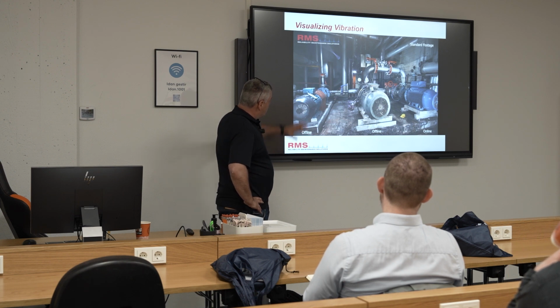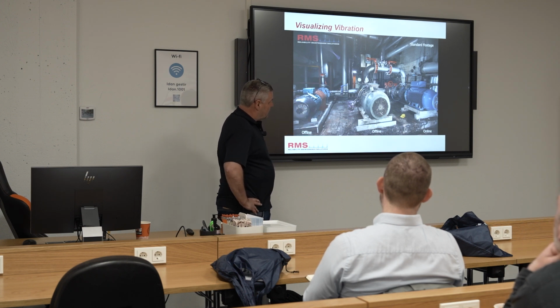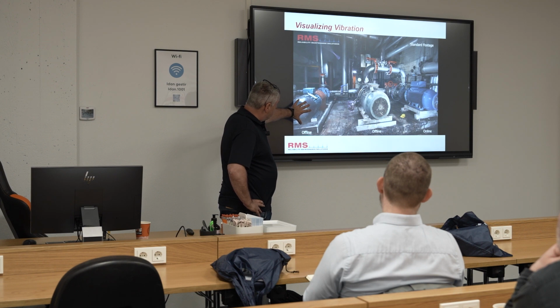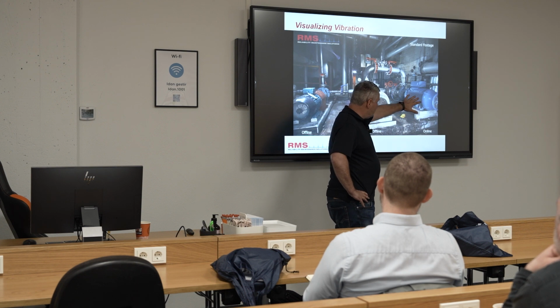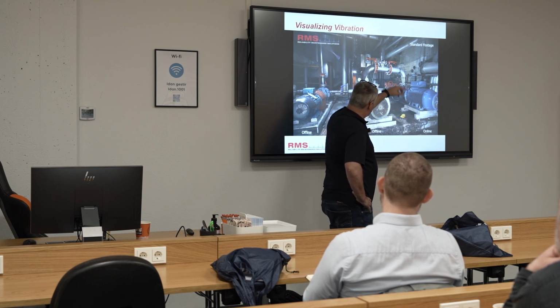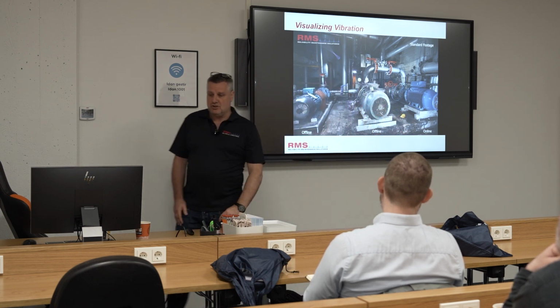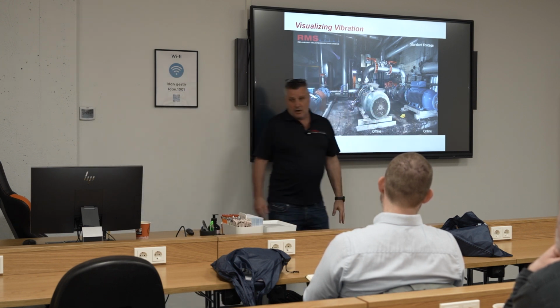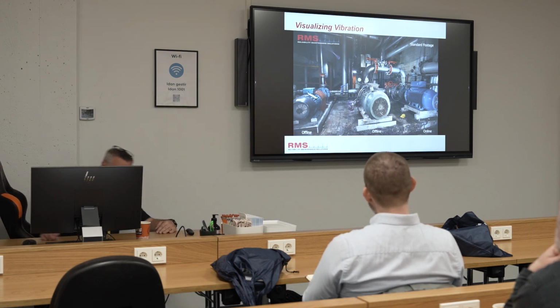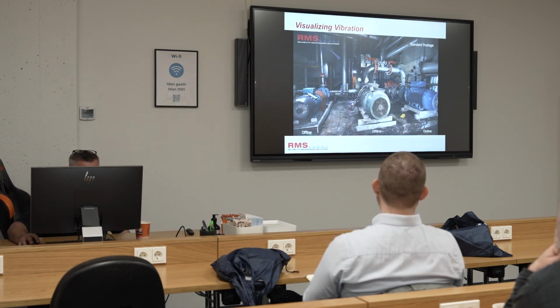exactly happening. Now in this instance there now we're going to show you a situation where this is a British sugar plant in the basement of a cellar where you've got a motor that's offline, pump set, and a pump set that's offline. The only one that's running is this new pump over there that they put a new motor on, but the primary part of this maintenance repair was to put a new section of pipework in there. That's all they were interested in. Not once did it cross their mind to look at the base plate and look at the poor situation it's running in. Fundamental repair was this piece of pipework up there. Now, let me just play you the scenario off here. So we've got two pumps offline and one online.